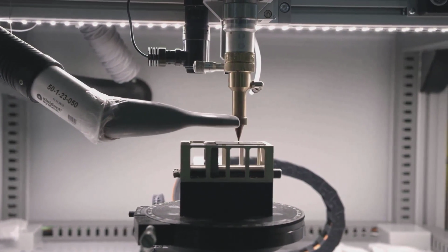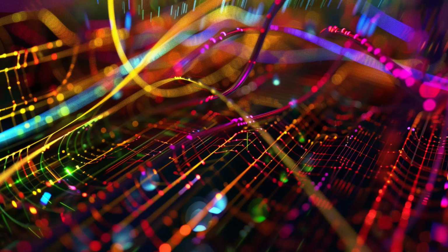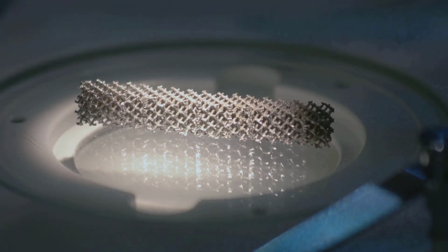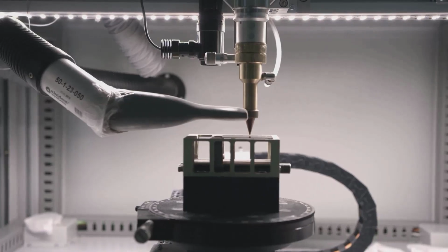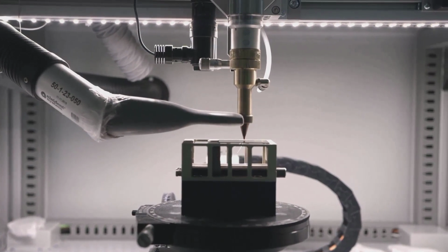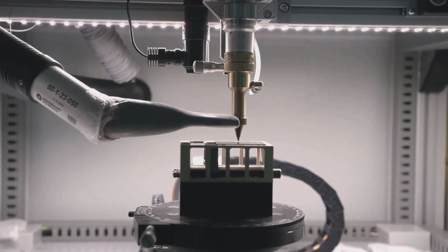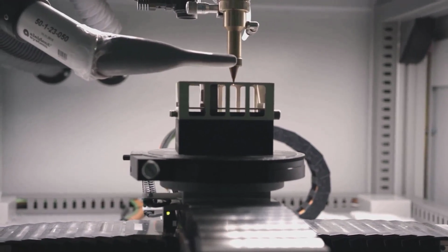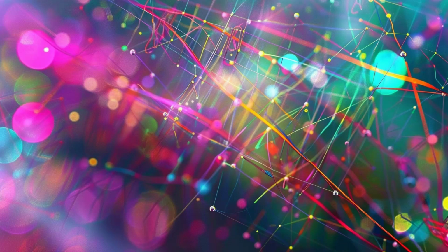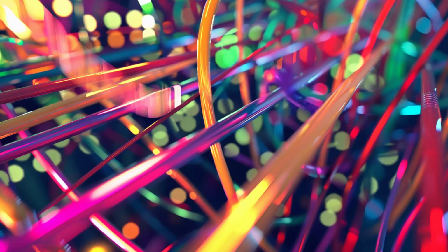Techniques such as lithography, etching, and electrospinning fall under this category. Lithography uses light or electrons to pattern a photosensitive material, which is then developed to reveal the nanostructure. Etching, as the name suggests, involves selectively removing material to create the nanostructure. And electrospinning uses an electric field to create fine fibers from a liquid. Each of these techniques has its own advantages and limitations.